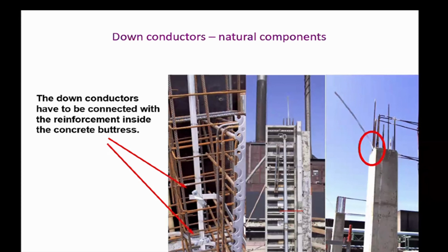And I recommend GI tapes more than copper tapes because at the moment, there are some conflicts between the standards as well. My research students found that there is no problem of having GI tapes, and copper tapes may have some more problems. But some people say that you can use copper tapes. We can have a separate discussion in this regard.